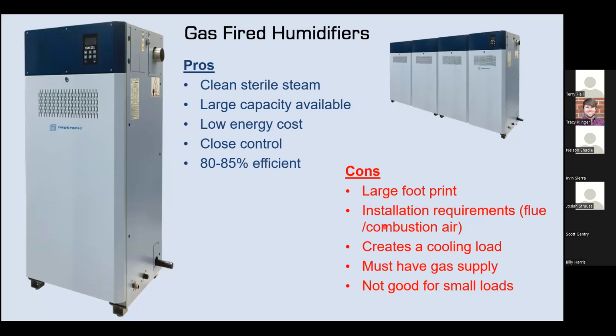However, with our humidifiers, the larger you get in size, basically what we do is take multiple heat exchangers and tie them together into a single controlled humidifier, and they can operate independently off the main controller. You get better turn down with the larger humidifiers because the turn down will be the minimum output of a single module. So on our largest humidifiers, you may be looking at 20 to 1 turn down theoretically.